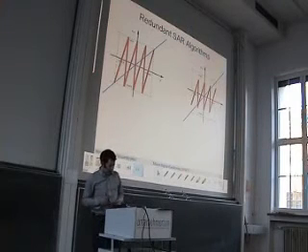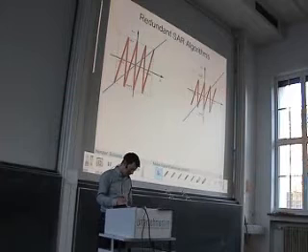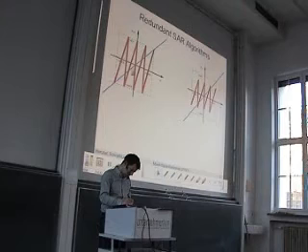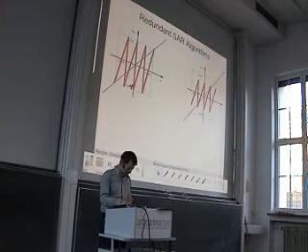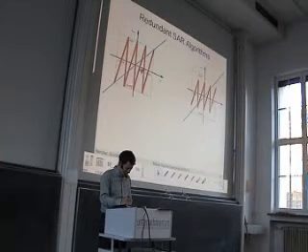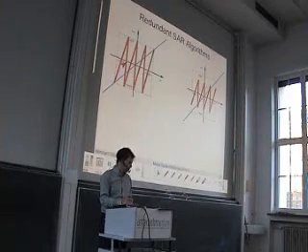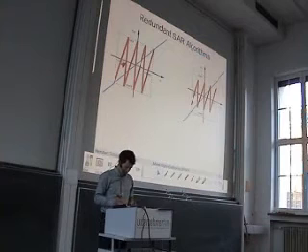Choosing more than one threshold leads to the left picture. Here you can see we have not only the threshold at position 0, but we have it also at plus Vref over 4 and minus Vref over 4. So this is something that is represented by this more general pipeline stage that I sketched.